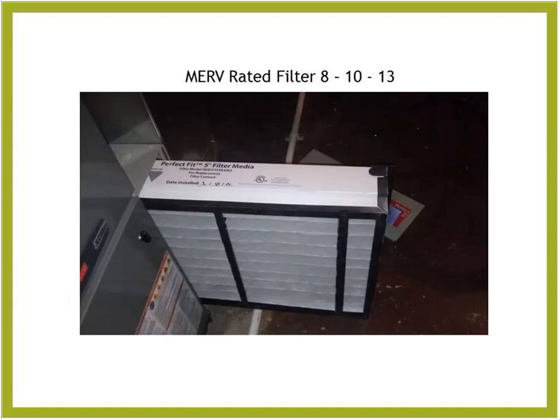We recommend starting at MERV 8, and anything beyond that can actually reduce the efficiency of your heating and cooling system a little bit, but it can increase the filtration of those units. What these are filtering are bacteria, mold, pollen, allergens, VOCs, depending on how high a level. You start to get above 13 and you're looking at hospital grade filtration, and so if that's important to your client, you can put those systems in there. Just make sure that the HVAC system is designed to handle that.